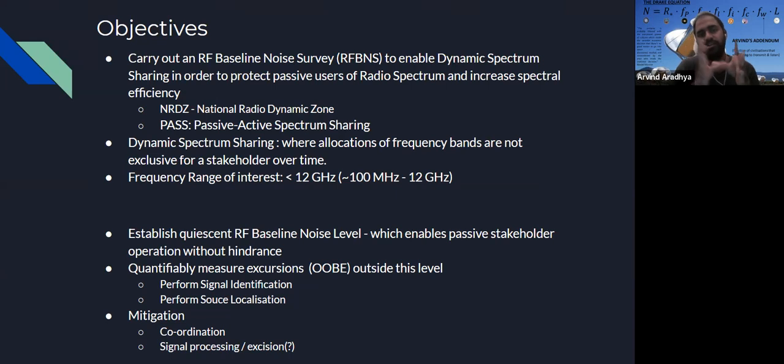And there are certain regions of spectrum which are protected for use by meteorology, for use by radio astronomy, for use by communication. So there are parts of the spectrum where you can't transmit because that spectrum is being used by the military, for example, and you can't transmit with commercial mobile phone communications in that region.